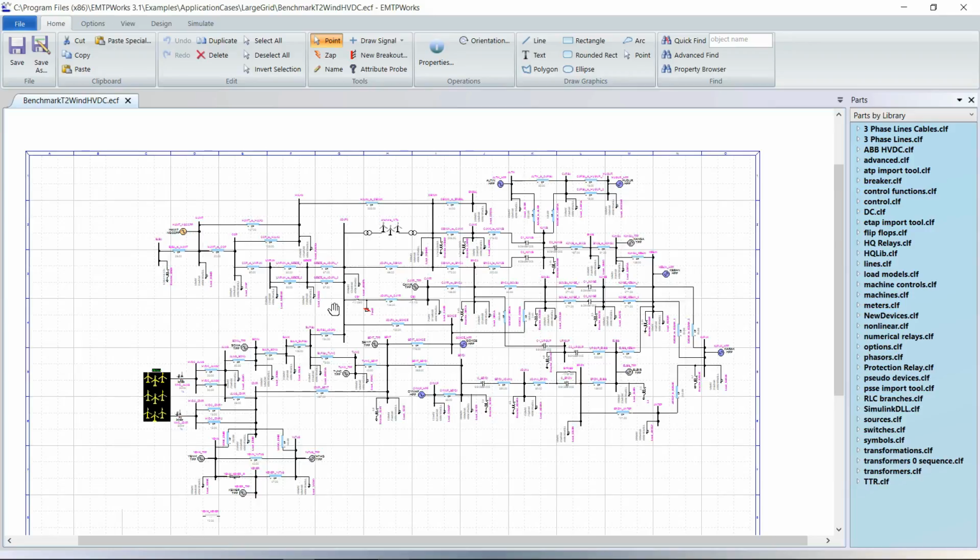Well, the first thing is now you have access to this level of precision for a long simulation. So why won't you use it? Why would you keep using approximation, only work with the positive sequence? Hey, you are in the phase domain. You have access to a very high precision, and it's fast. So for me, that's a good reason to use a transient software to do that. Here also, the goal of such a simulation is actually to make sure that the control of all the different machines, of the different wind turbine, HVDC, how they all react together after an event. Okay, so that's actually the real goal of doing that in a transient software, because the models of wind turbine and of HVDC of a transient software are way more precise than every other kind of stability package.